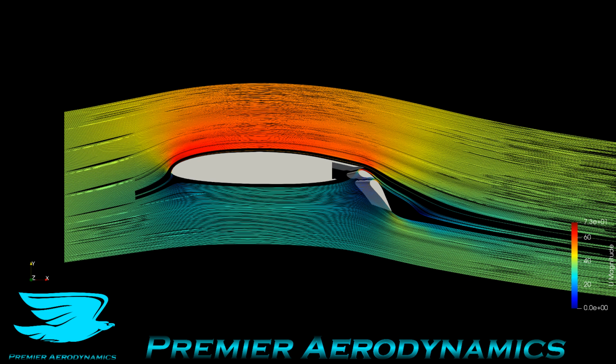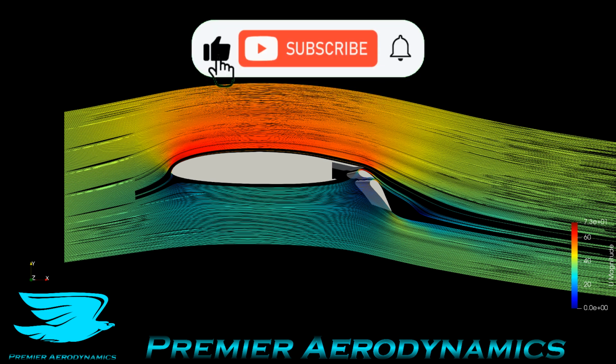Today we're looking at how a wing flap system works. So we have a regular airfoil and we have two other elements behind it. So this is a three-element system effectively. The first part is the bulk of the airfoil. Then we have two smaller airfoils effectively that operate with the aerodynamics to increase the lift coefficient of this system